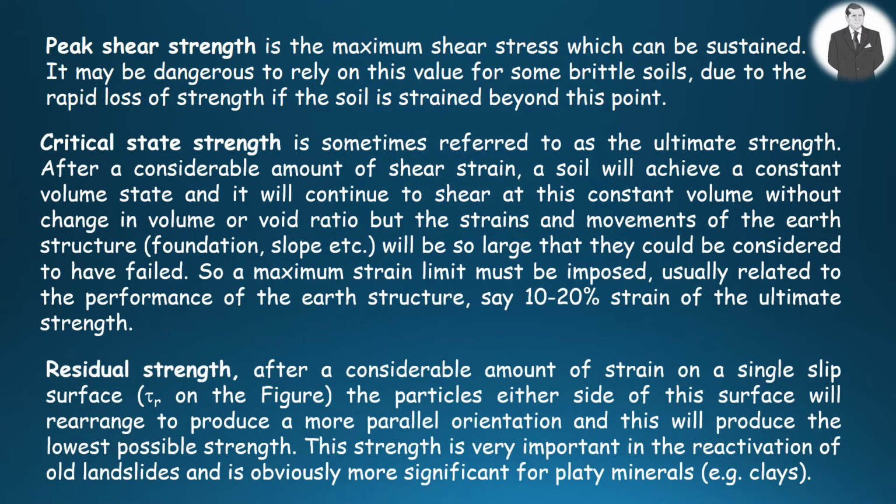After a considerable amount of strain on a single slip surface, the particles either side of the surface will rearrange to produce a more parallel orientation, and this will cause the lowest possible strength. This strength is very important in the reactivation of old landslides, and it's obviously more significant for platy minerals, for example, clays.